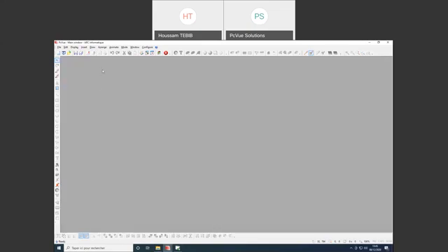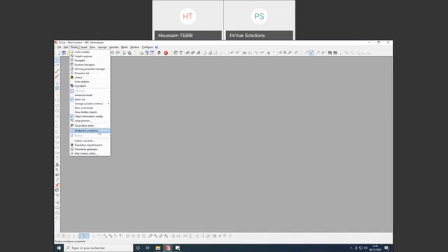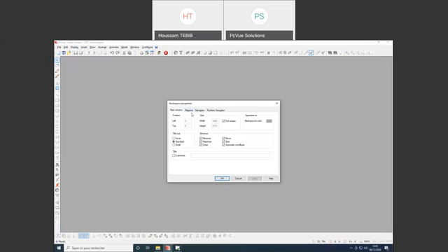Okay. So now I will close all these mimics. And first, to configure the multi screen, you need to go to display and workspace property. Here you have a region tab. And the first thing is to choose a number of regions. You can choose 1, 2, 3, or 4 different regions. We choose, for example, 2 regions. Then you have to choose an orientation, for example, horizontal or vertical. Vertical, the bottom and the top, and horizontal, right and left.